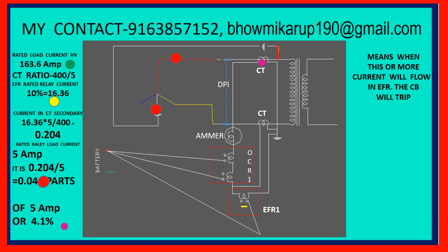Immediately both circuit breakers will trip to make the transformer dead, because an earth fault near the transformer coil is very dangerous. There is almost no impedance, only the transformer impedance. The current will be enormous. So it will trip both the circuit breakers immediately.